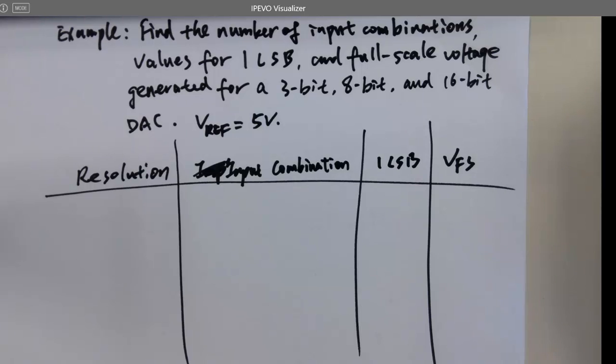But if I'm doing capacitance sensing or anything else I can think of, do we need a high resolution ADC for temperature? Usually not, right? Do you really care about a 0.01 degree change? Acceleration is one example. You need a high resolution for acceleration. Force, okay? Scales, force. And capacitance is something that really needs a super high resolution.